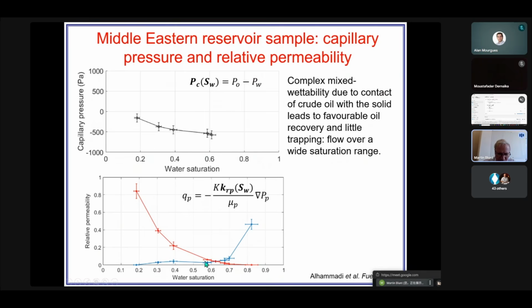characteristics have this low water rel perm, but I'm not going to ever get to this true residual. I'm going to get to a saturation around here, close to where the relative permeabilities cross. So actually, this is a case overall that is quite favorable for recovery, but it's not quantified exactly by the residual saturation.